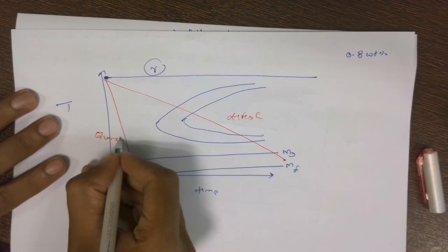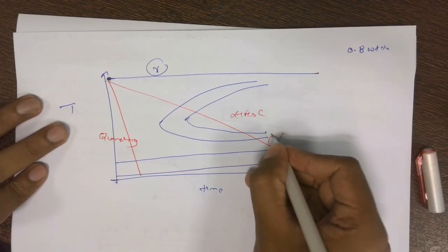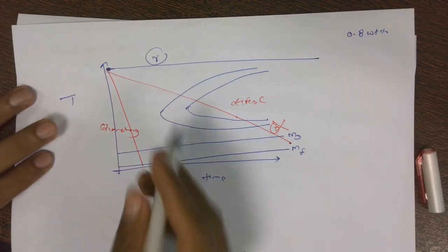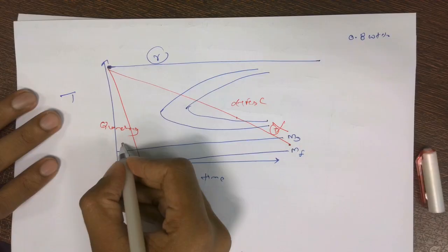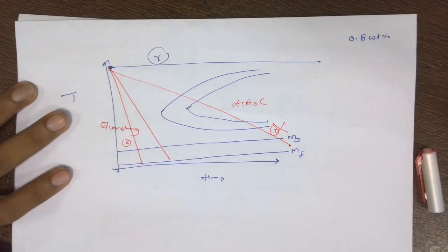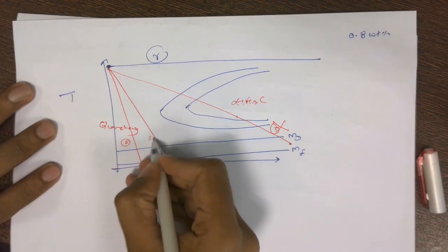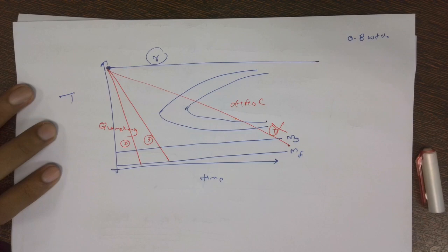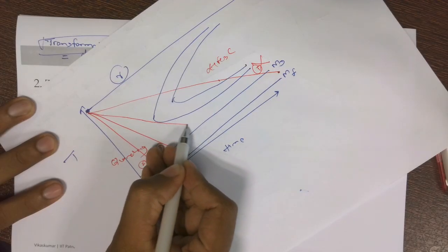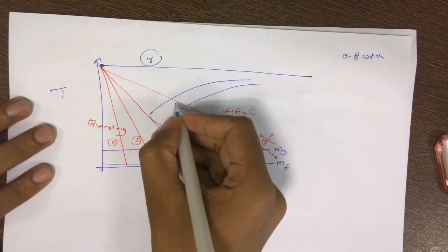Now, this. Will I get martensite here also? It is not crossing the C curve, right? Third one, we'll get it, right. That is also true. How about if I go very close to the nose? I am not cutting any of the phases, for example, austenite converting to the pearlite phase. Here will I also get the martensite? Yes, because I am not touching any of the other phases over here.